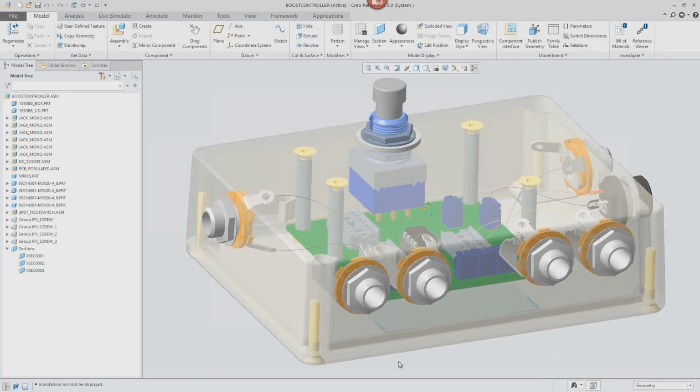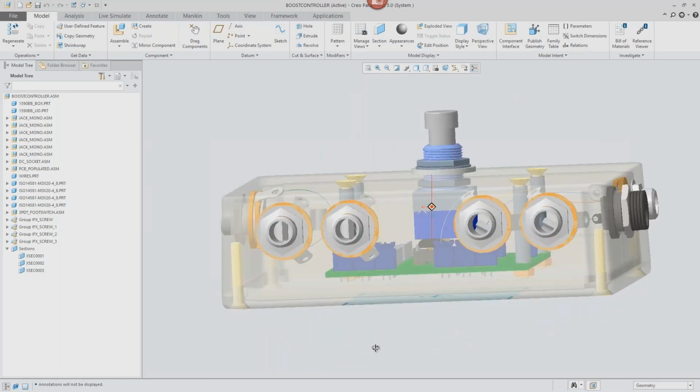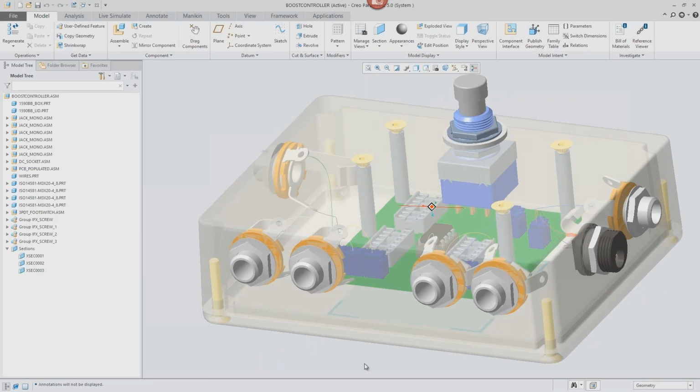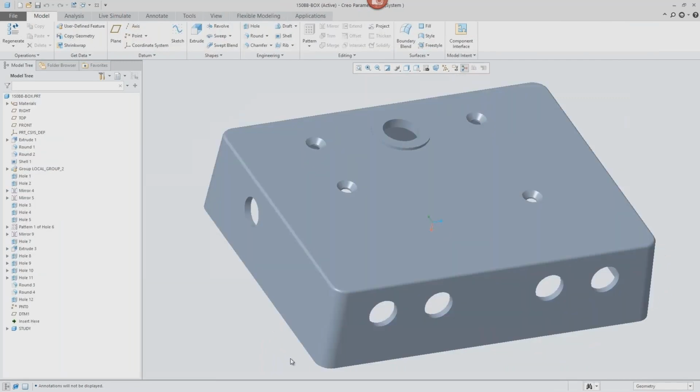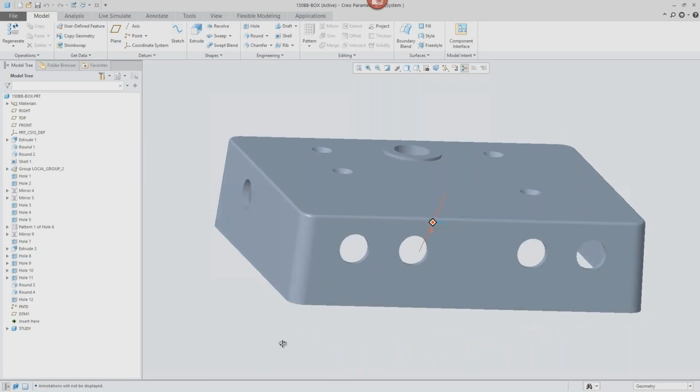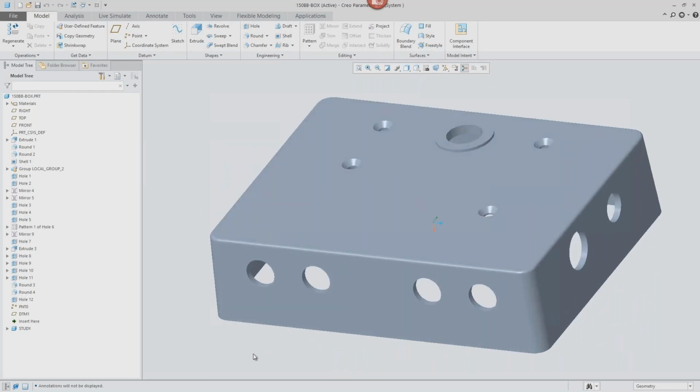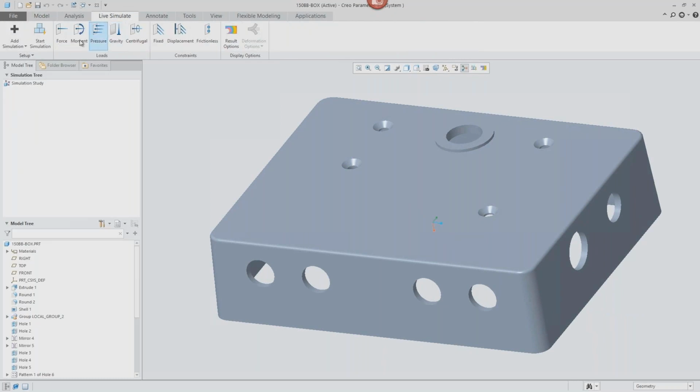Traditionally, since this is something that's going to be stepped on and has to withstand the stomping that a musician does throughout their whole set, it might be made out of something like bent sheet metal. But I want to explore an alternative design, maybe make this out of ABS. Maybe we're going to 3D print this in plastic, or maybe it's just cheaper to make this in plastic. But it's important that this still holds up to the structural impact we're going to put this under as it goes through its life cycle. I'm concerned with the force of someone stepping on this, compromising the housing and maybe snapping it in half.